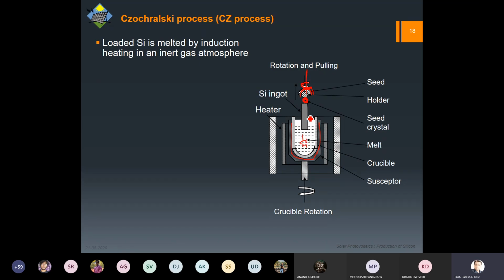So this liquid is getting converted into the solid. For liquefaction we require a heater. Now, the seed we are going to use is deposited with some deposition process, and it has a very precise atomic arrangement, let us say 100 or 111, whatever we desire. This seed is very small, but the atomic arrangement is perfectly what we want.